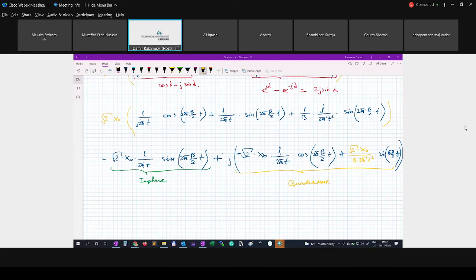So the task is the following. We have a complex baseband signal, a low pass range signal, given by this expression, x subscript L of t equals the psi function, and we need to calculate the corresponding bandpass signal x of t if the carrier frequency equals 5 times B. And then we need to determine the spectrum of this bandpass signal. Let's try to do this.